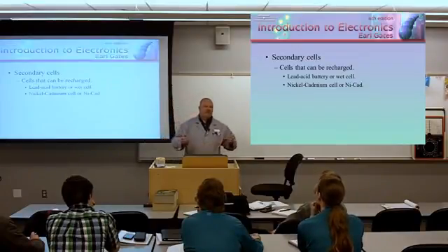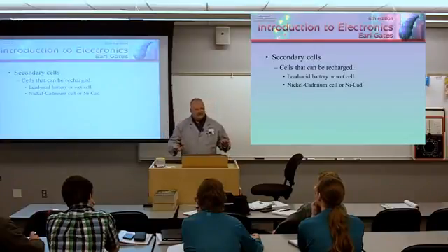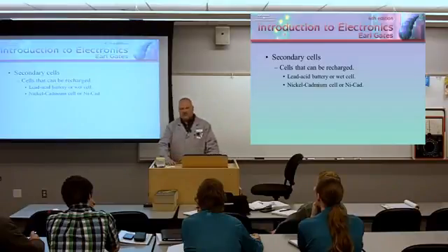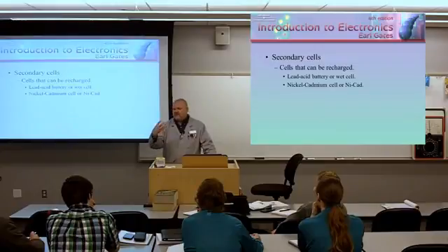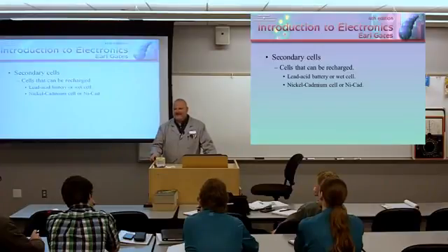So the captain figures we're going to do some nuclear drill, scram the reactor, pow. Normal procedure is we start to come up to periscope depth, make sure that we're not going to hit anybody up on the surface, come up, raise the snorkel mast, start the diesel generator. Well, they try starting the diesel generator, which was commonplace, and it wouldn't start. What had happened is there was this multi-pin connector that for whatever reason disintegrated in the back of the diesel control panel. So it's like, well, that's going to take 2 days to put back together, you know? So we're on battery power.